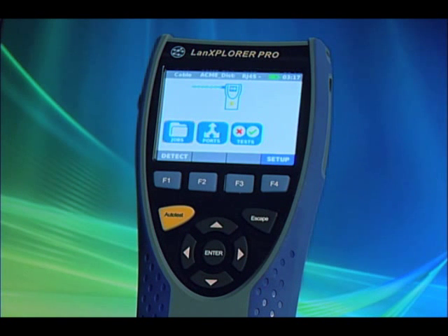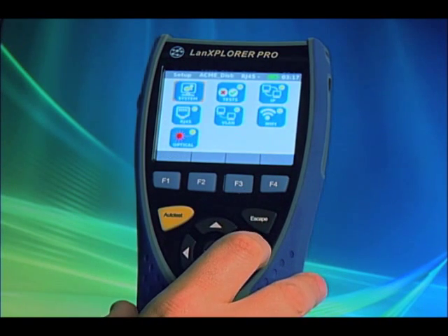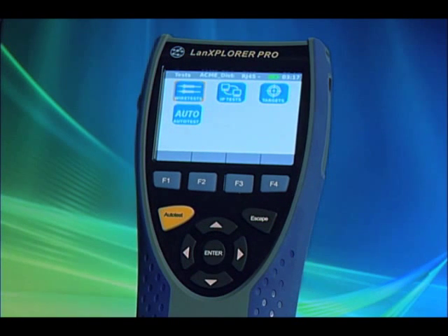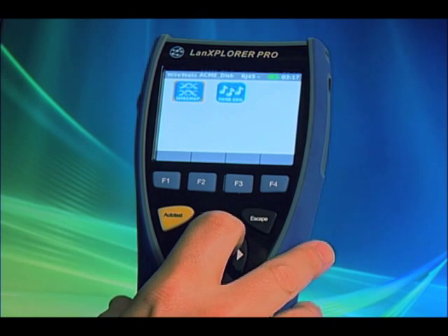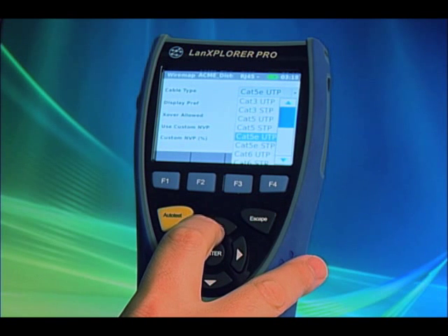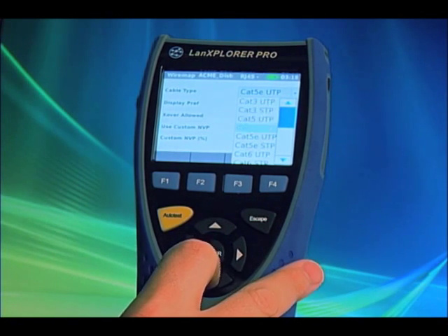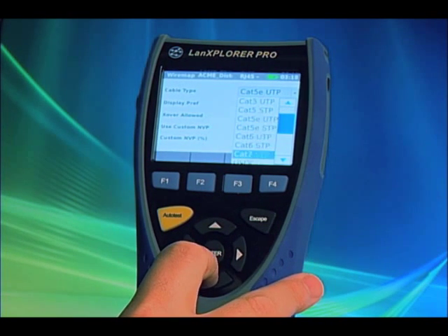Configuring unit tests. Go into the Setup screen. Select Tests here. You can select the wire test preferences, IP tests, targets for ping and trace route tests, and the auto test preferences. In wire tests, you can choose your wire map configuration, the cable type, all the category types, and all pair 4 tests. You're merely selecting what is listed in your saved test documentation.